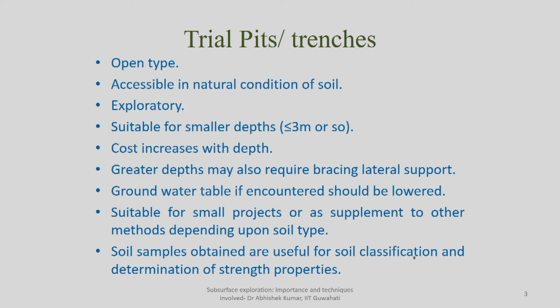If you go for deeper depth, the cost will increase, because you have to make more arrangements to ensure that the soil does not collapse into the trench pits. So, greater depth may also require bracing, because not every time you will have cohesive soil. At times you have to retain the soil which is surrounding or lying on vertical or close to vertical faces. You have to retain the soil in its intact position, otherwise the soil will fall and you will not be able to collect the soil sample from deeper depth. So, you have to apply some kind of bracing, that will be a kind of lateral support. It can be in terms of shells, it can be in terms of anchors, or different ways are there if you are going for very deep trial pits.